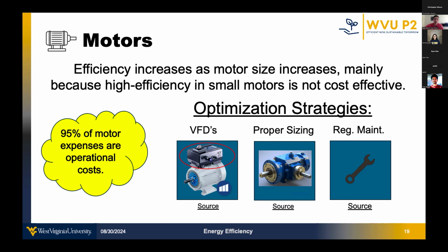And lastly, it's not mentioned on the slide, but VFDs do come with soft starters, like I said in the previous VFD slides, and these are used to reduce the inrush current during motor startup. This not only lowers electrical stress on the motor, but also reduces the overall energy consumption during the startup phase. Soft stops also come with VFDs in some cases, which will reduce the overall energy consumption during the shutdown phase.